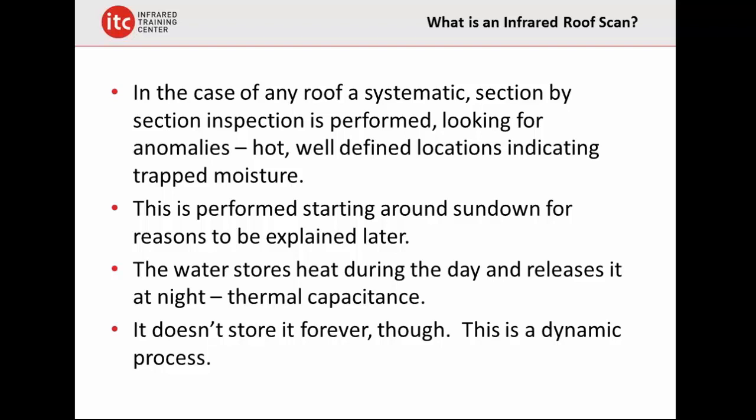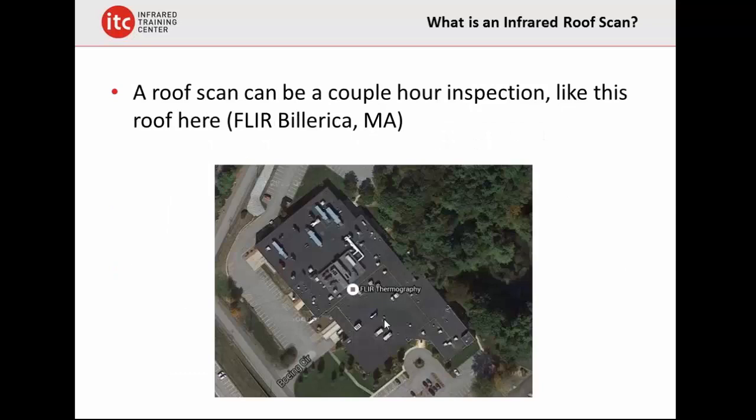Now, when we go up onto a roof like this, you want to be systematic. So when we come out through here, this roof actually has 3 or 4 sections, and we would take each section of the roof and go clockwise around through here. When I used to perform roof surveys as a consultant, I would go around the perimeter of that section first, looking at the parapet, looking at the flashing, because that's a good source of roof penetrations. I would do first a perimeter sweep, ignoring all the stuff that's in the middle, stuff that would be obvious. But I would want to make a complete circuit of the entire edge of the building, keeping in mind all of the fall protection setback standards. You should stay 6 feet away from the unprotected sides and edges.